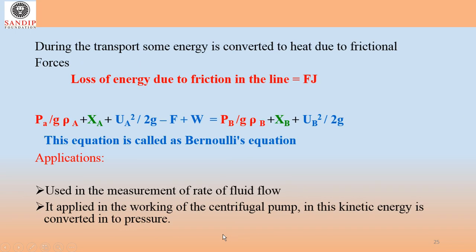As the energy is added, during transport some energy is converted into heat due to frictional forces. That loss of energy is given by F. So in the last equation you have the loss of energy as minus F and the energy added as plus W. Simply add minus F plus W and write the same equation, and this equation is called Bernoulli's equation.